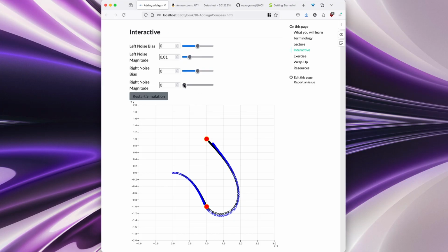I haven't modeled noise perfectly in the simulation. In fact, there are multiple sources of noise, from the sensing side on the wheel encoders to the actual slipping of the motors themselves, or the inaccuracies of the motors themselves. Instead, I just packaged those all together and said that the left motor will have some noise to it from both the sensing and actuation side, and so will the right.